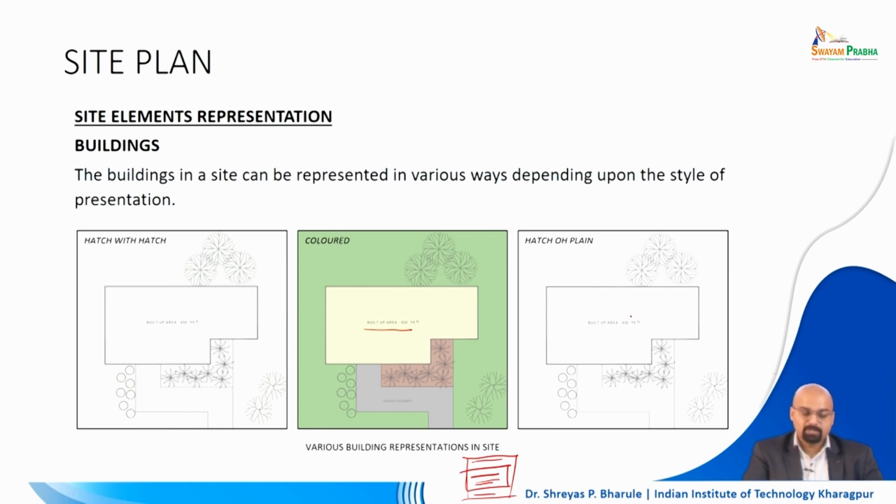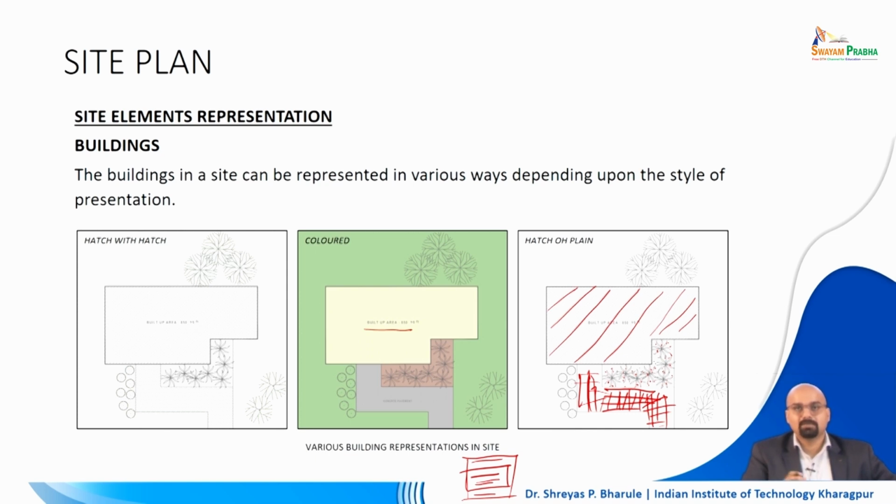types. So, here you are going to represent, say, this particular area is my building, right. This area is my softscape where I am going to put my flower planters or things like that, or I am going to plant my trees. So, this has a different hatch, and then you have some typical type of hatching for the road, and that is all. For all the places where you do not have a hardscape or a softscape, all of that will not be hatched, right. So, these are the variations between these.